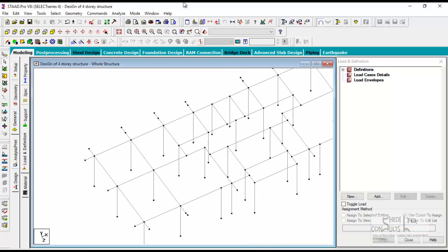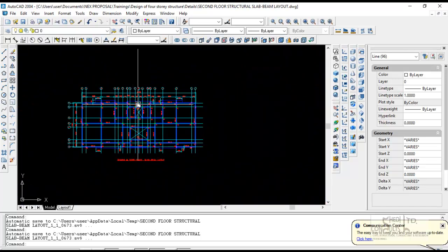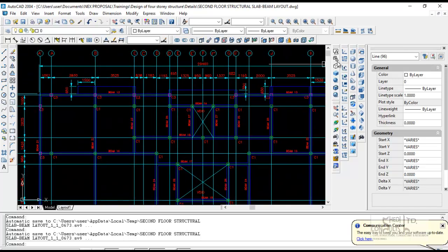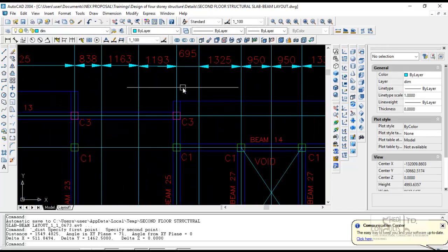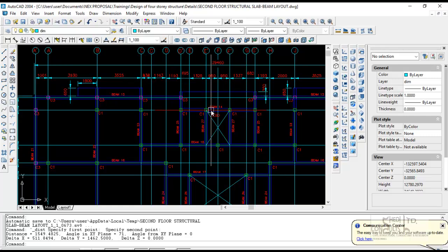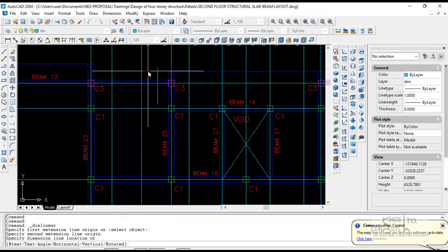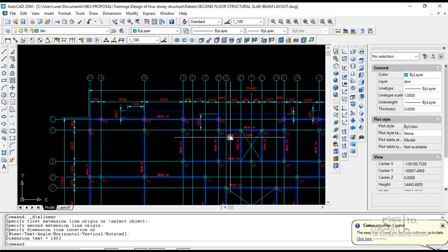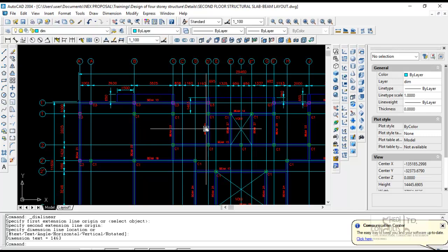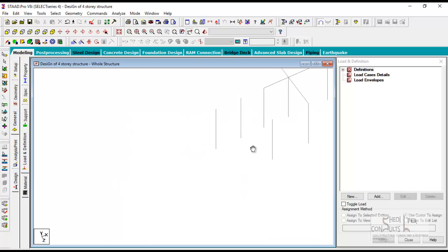So this is this member. Let's look at this cantilever that projects outwards. It's about 1.76. Let's just reconfirm. 1.76. Okay, that's here. Let's check from here to here. What I'm seeing is 1.462. Let's reconfirm from here to here. 1.463 or 1.4625. So something appears to be wrong. We need to check where the problem is from.